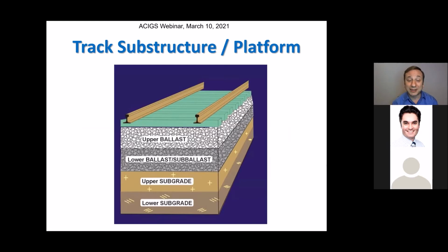When we talk about ballasted tracks and the track substructure, these are the multiple layers that carry all the load, especially ballast and sub-ballast, which are granular materials that are supposed to distribute the load coming from the wheels, from the train rail, directly into the track substructure. The upper ballast layer serves the drainage purpose and also lateral stability, holding the sleepers and the rail in place. But at the same time, subballast often is a separation layer that provides an intermediate layer of separation, an intermediate layer of drainage in a way, not allowing fines to come into the ballast layer, right?